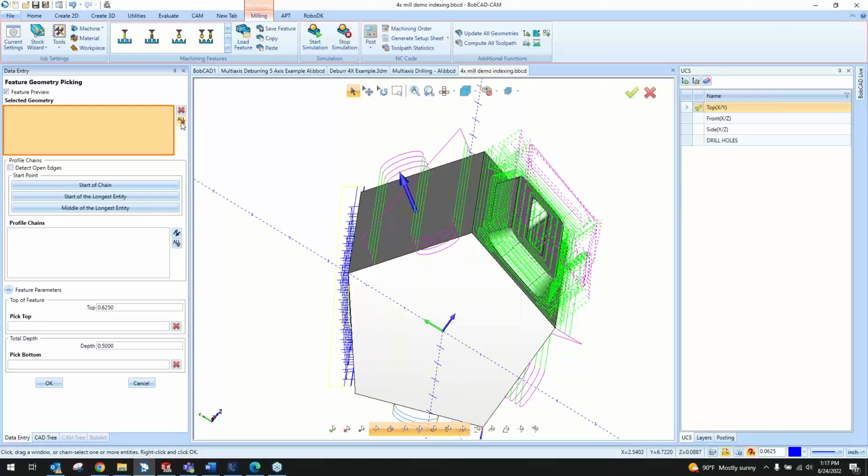One technique that we use quite frequently to help save us time, if the geometry is a little more complicated than this rectangle, is to right click on a surface edge, and we've got two options here to chain select surface edges. Constant Z would be selecting all of the surface edges in the same Z direction of our index here.